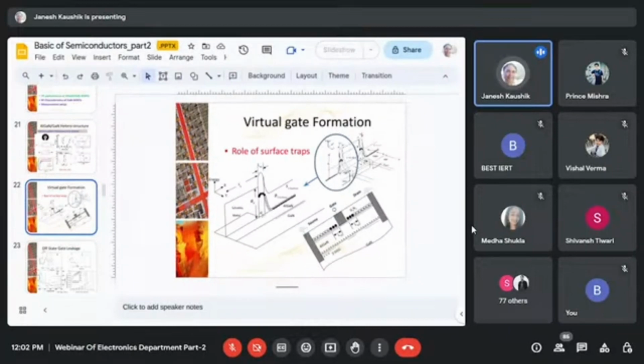That prevents us from using a highly doped layer at the top surface, and that is why our surface states are not satisfied. Either we use silicon nitride as a passivant, which does not passivate our surface states completely, and we get this virtual gating effect. In addition to that, we get leakage current also, because if we have controlled the surface, we have controlled the conductivity there.